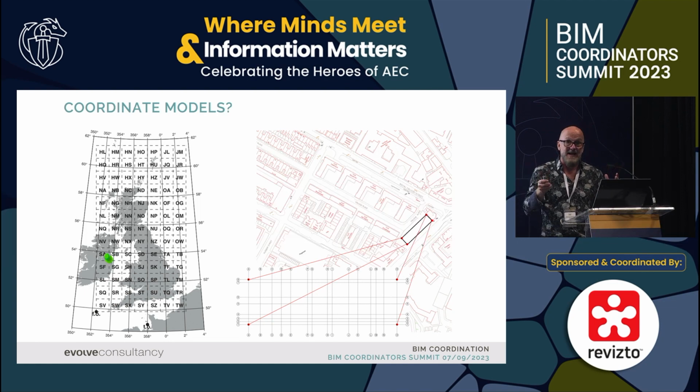Do it at stage 2 when you know who the design team are, you know where the coordinates of this project are going to be. It doesn't matter if it's exact, but get them to model a cube. It can be 1 meter by 1 meter. So long as they all get it in the same place, you've got a placeholder then that you can get this right. You cannot clash detect, you cannot coordinate information if it's not in the same space.